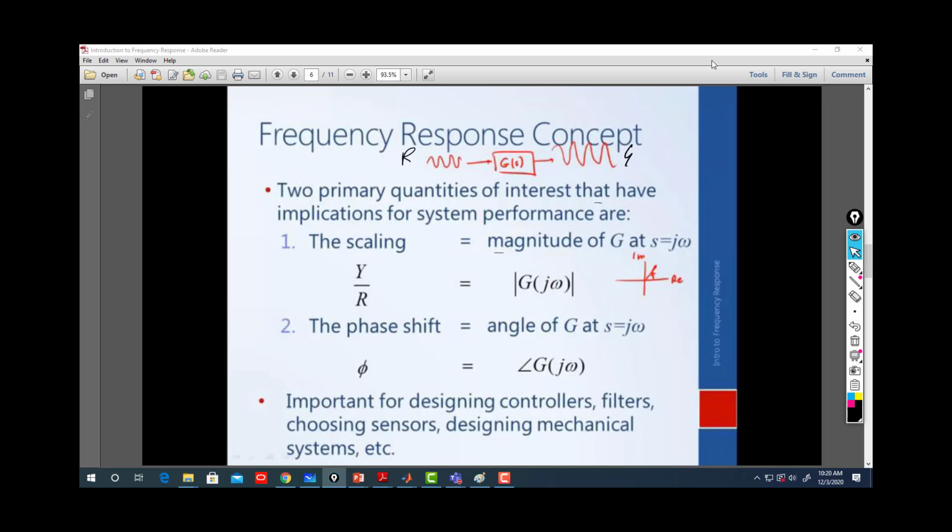If the noise coming from the road has a frequency equal to the frequency of your suspension, then your car will vibrate a lot. So you should avoid that. When you're designing your spring for your car, you put the thickness and the length for it at a certain natural frequency.